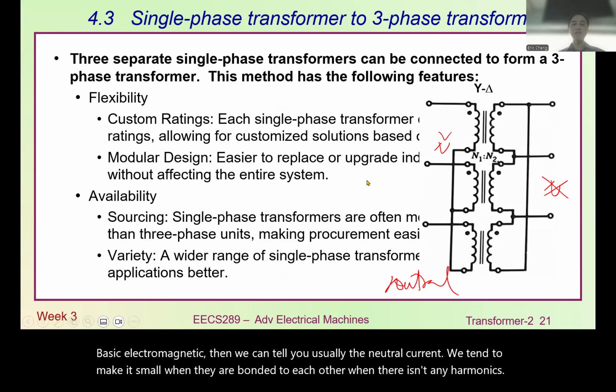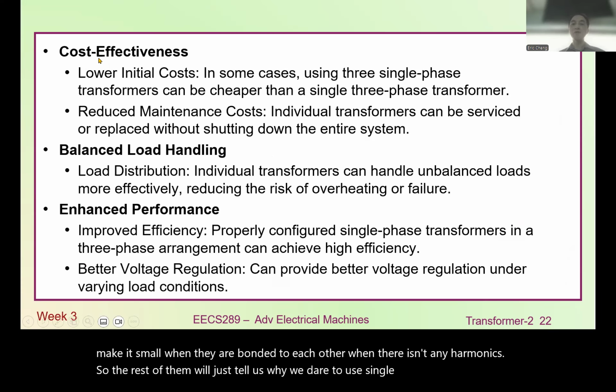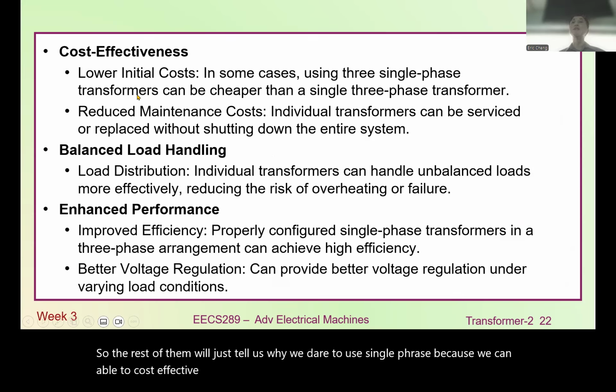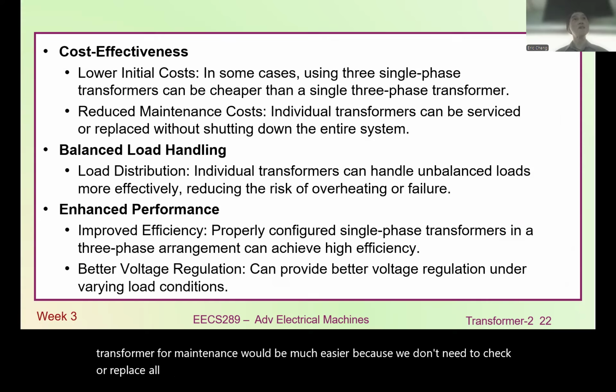So the rest will tell us why we like to use single phase transformers: they are cost effective compared to a three-phase transformer. Maintenance is much easier because we don't need to check or replace all three transformers. If any one winding is broken, we can just replace that particular transformer.